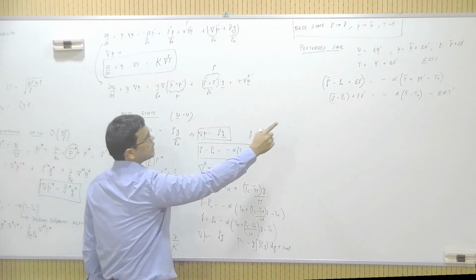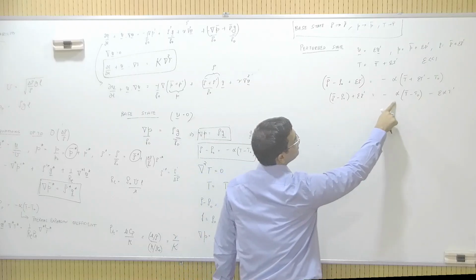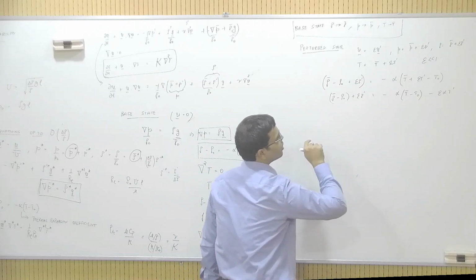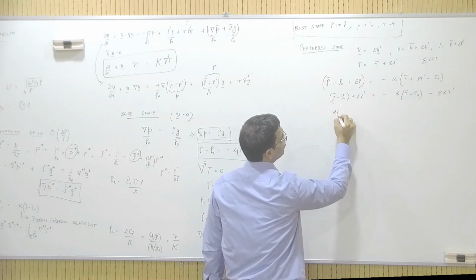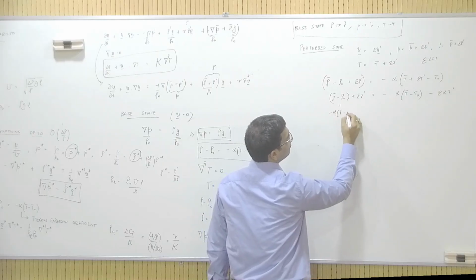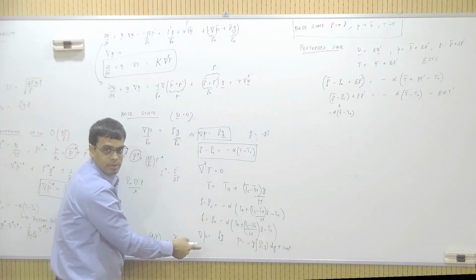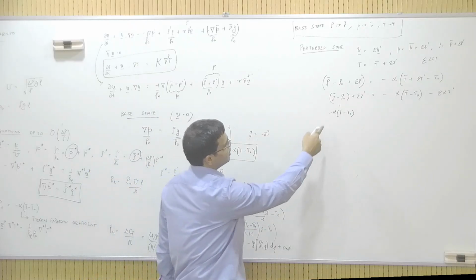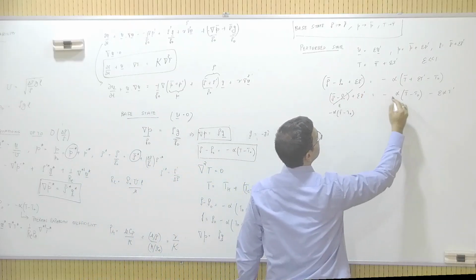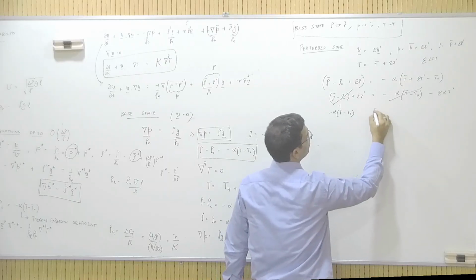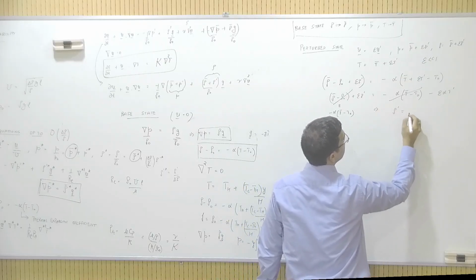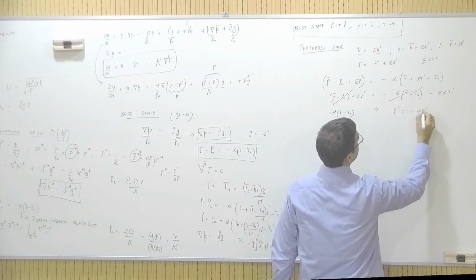Now notice that rho bar minus rho naught is equal to alpha times T bar minus T naught. Okay, this is equal to alpha times T bar minus T naught. That's how we solved for this rho bar. That is how we evaluated this rho bar. So these terms basically cancel out, and from here you get that rho prime is simply minus alpha T prime.